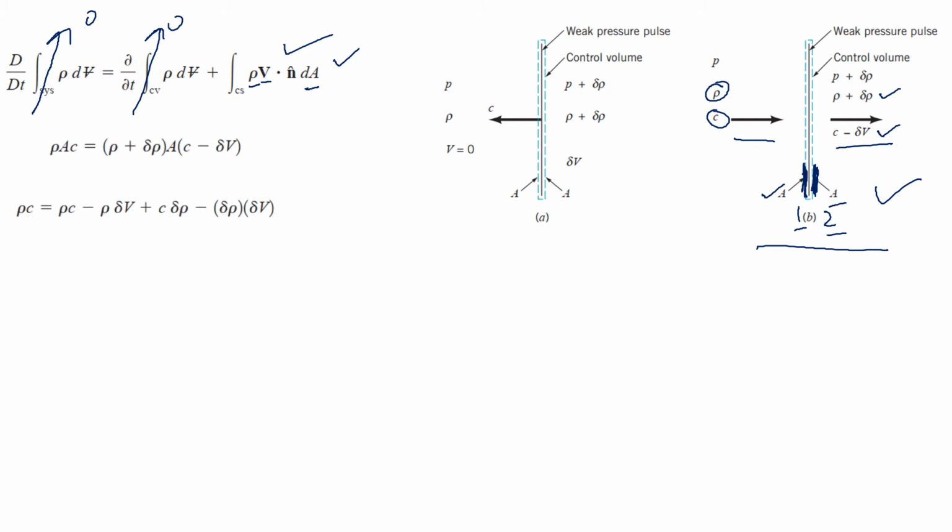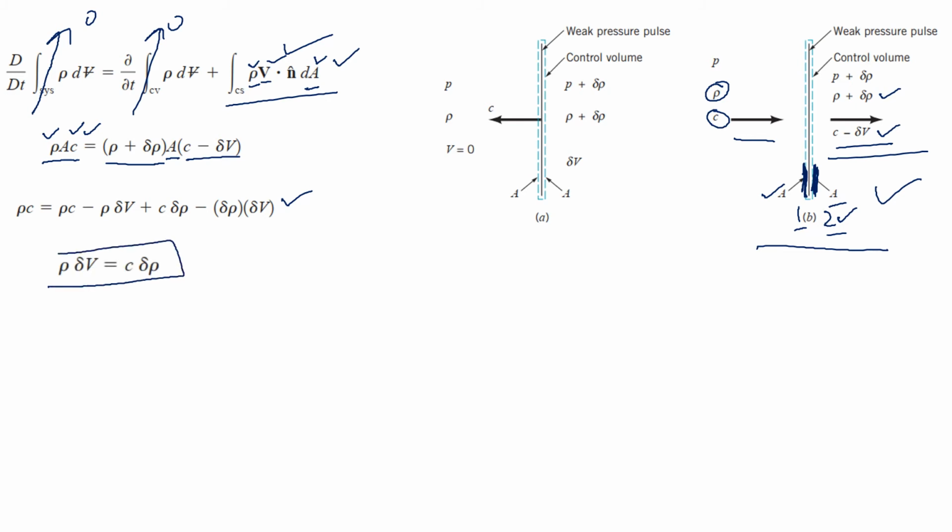So this is at the inlet, this is the density, area, and velocity. As you already see, density, area, and velocity in this term, and here the change in density at section 2, area, and the change in velocity at section 2 right here, as we already mentioned. We are going to rearrange these terms, multiply these terms, and then rearrange this equation like this, and after simplifying certain terms, we can write this equation like this. This is from the conservation of mass.